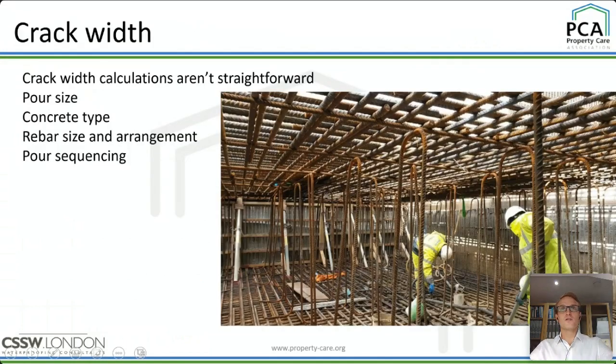So what determines your crack width? Well, I've already said I'm not a structural engineer. I don't design rebar and I wouldn't do crack width calculations, but my understanding is your crack width is affected by many different things, including what is your rebar, where is it, what's your cement binder, what is your pore size, where is your pore? So that would be affected by your edge restraint or your end restraint. All of that's going on.